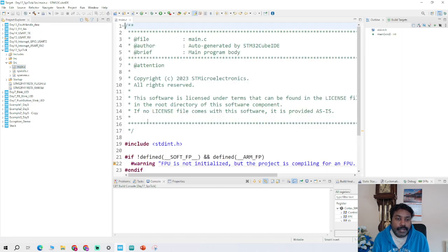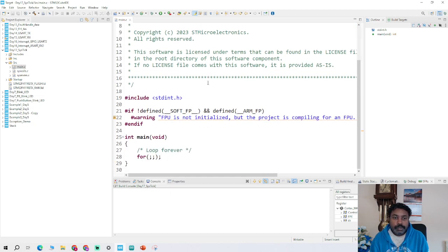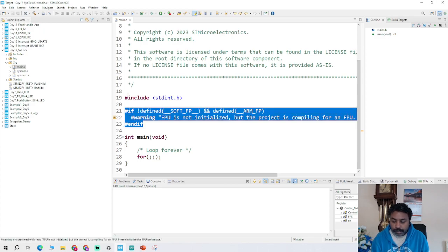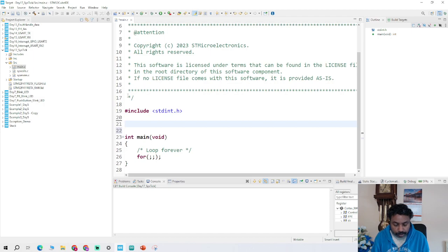As you know, this section is for reference to say what file it is, so you always need to give the file name .c and also the author who has written this program and what it is for. You also need to give an explanation indicating where this program is going to sit, whether it's in the main program or in the top section or the bottom section of the whole lengthy program. You need to say that. And this is a little bit about the license, to tell that you are using the licensed STMicroelectronics board. So go into the program. I will delete the internal default files and we'll start from scratch.